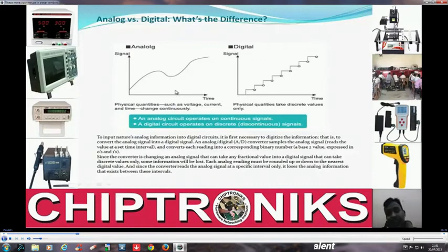In the schematic diagram, we have an analog to digital converter present inside, for example a battery charger or an IO controller, because at the pins of the IO controller it will receive an analog voltage and an analog current, but inside the IO controller there is an embedded controller, and that embedded controller is a microcontroller. It works digitally, so it requires digital inputs. So we must have an analog to digital converter inside an IO controller, inside a battery charger IC. That's why I'm introducing this concept of analog to digital conversion.